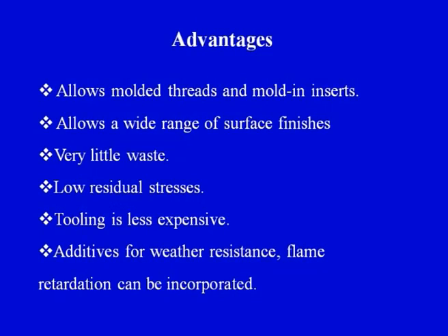And also in many of the cases, no finishing or no coating of the product would be required, because the integral surface finish that we get out of the process is sufficient enough for many applications. So the waste in this particular case is also minimized. Why? Because we are inputting the metered amount of raw material only, so there are chances of less wastage. So as it has been discussed that the metered amount of the raw material is put as an input into the rotational mold, so the wastage is minimum.